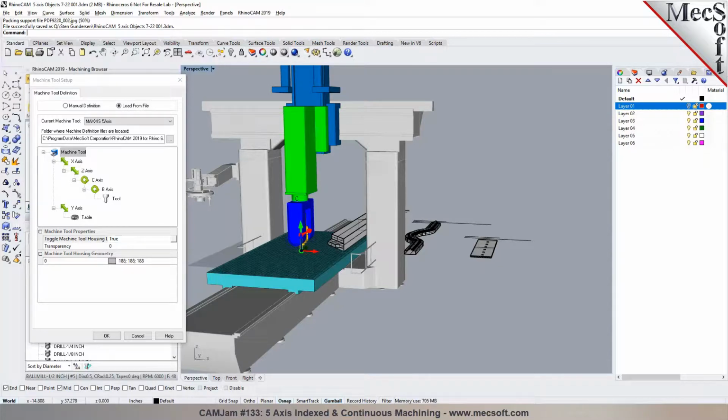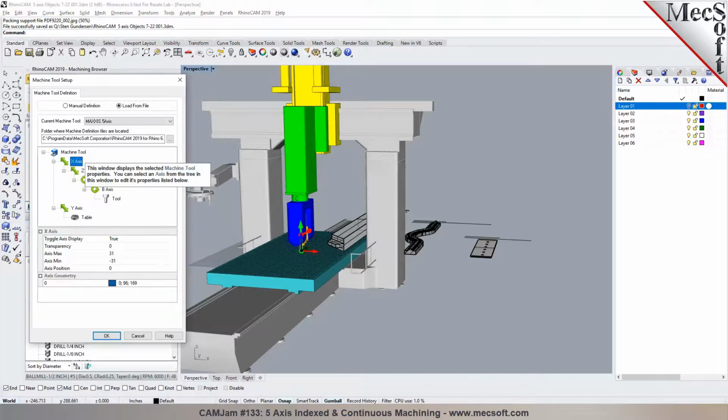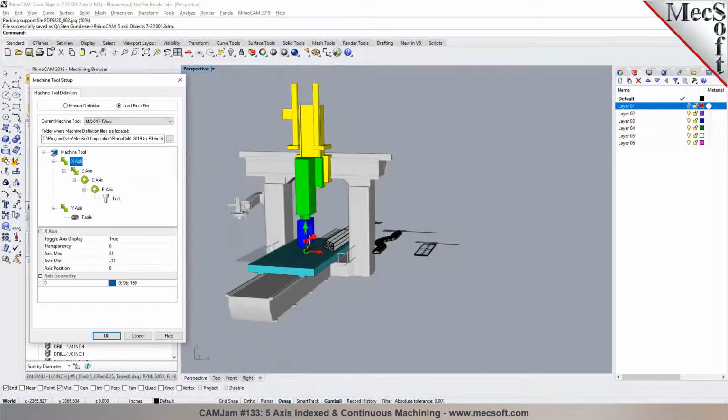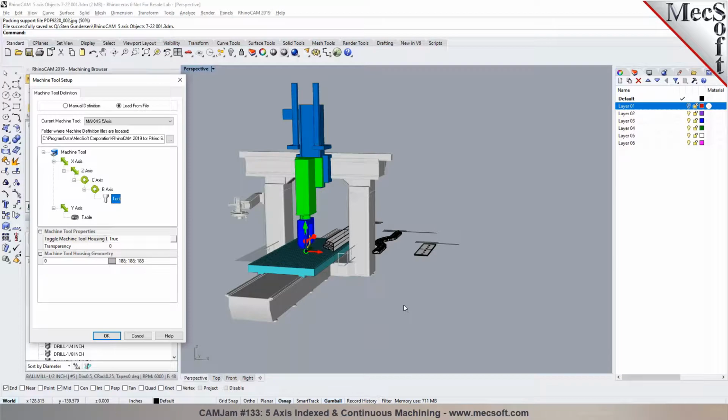It's something which we can certainly build and add the machine tool models. We would need the necessary machine tool model in here, and then we can add it to the list. So we need the different components like the x-axis, your z-axis, your c, your b-axis. Basically, these are all converted to an STL file, and then you can save it in this directory, and then you have an XML file which establishes the relation and the kinematics in here.